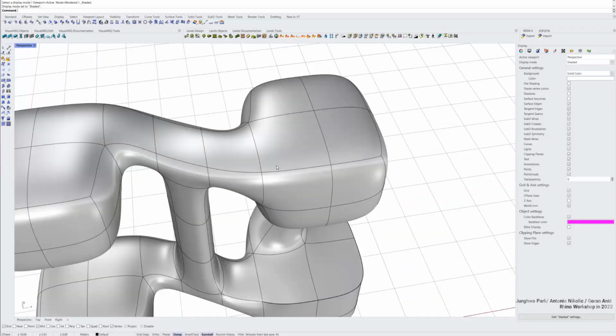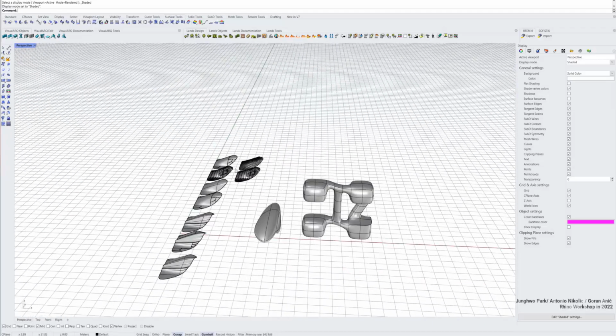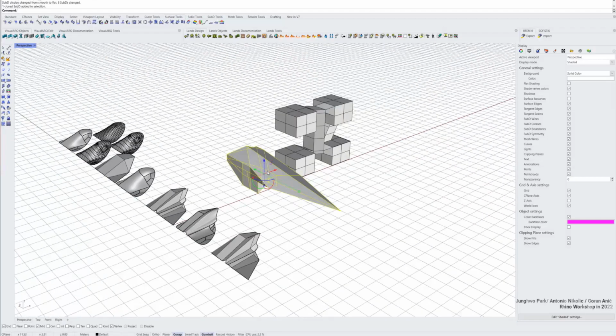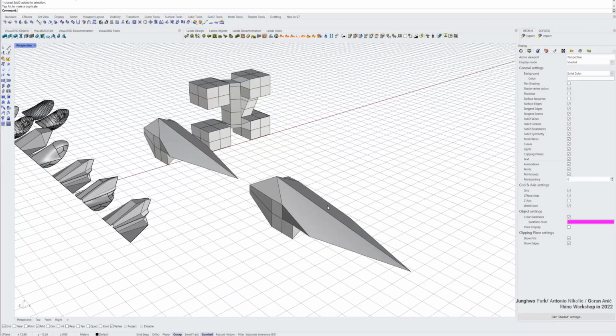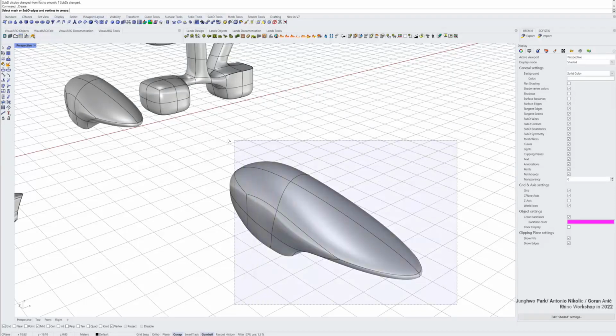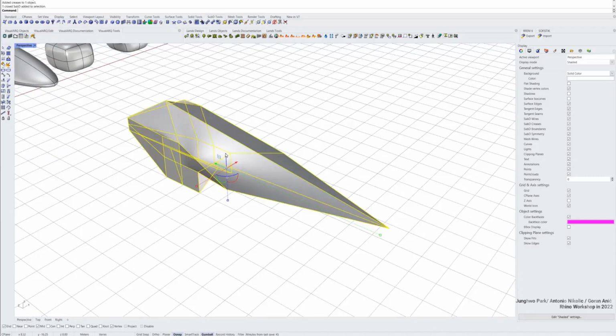And I think without using Rhino now, I remember, if you want to have this result without using Grasshopper, what we can do is crease them all. Then we get the result. So let me go to SubD, and we add crease to all the edges in here. Then this is actually creased geometry, right? Then when you convert to NURB, then you get